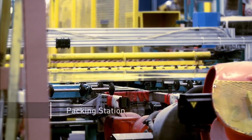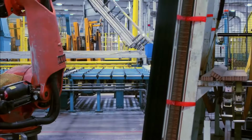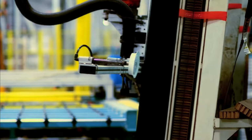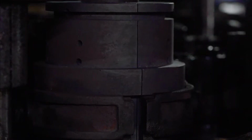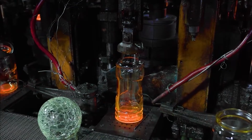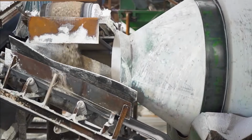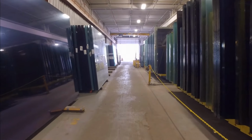Finally, the ready glass reaches the packaging station. The orders are carefully packaged, wrapped, and labeled. Float glass production processes can only provide glass in the form of flat sheets. The air is blasted from the inside to shape the glass into bottles, jars, or any other shape. This is why it's known as the glass blowing method. More or less, the batch mixing and melting of glass in the main furnace are similar to what we have seen in float glass manufacture.